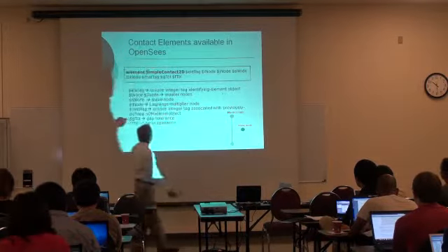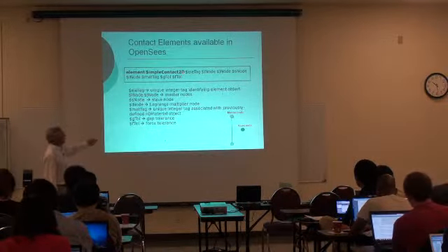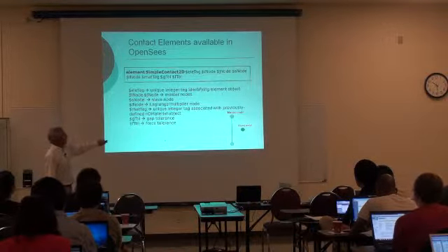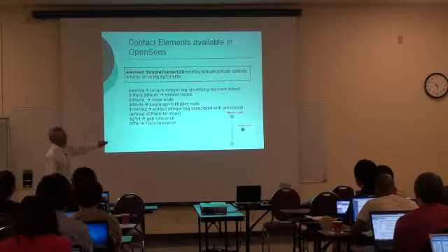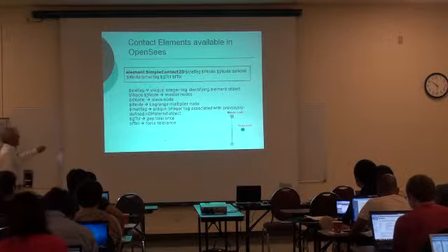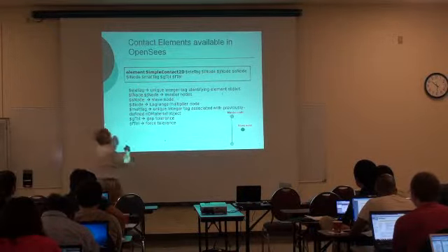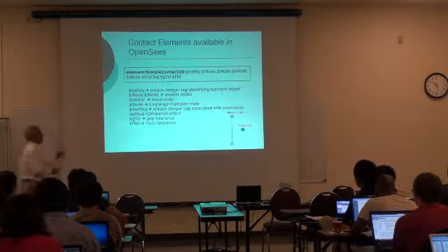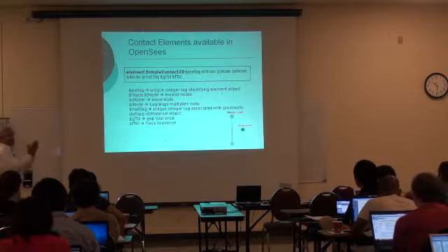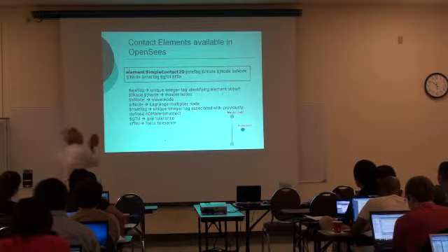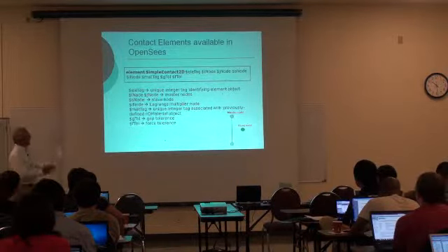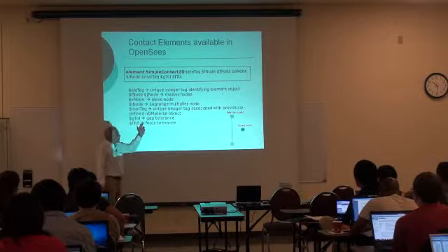And again, it's very simple. This is a simple 2D contact. You need to define the elements that are the master nodes. You also need the slave node. Because it's based on what is called a Lagrangian formulation, you need a Lagrangian node. But we have recently implemented a penalty formulation that doesn't need that element. And you have to define the material that will represent the frictional behavior at the contact interface. And you have some tolerances here, for the gap tolerance or for the force tolerance.